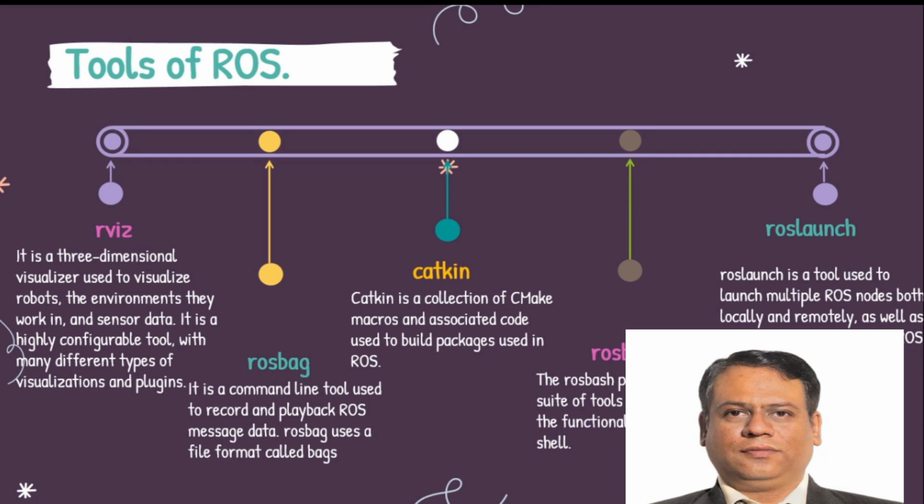And then roslaunch. roslaunch is a tool that helps to launch a ROS file. RViz is also one of the tools, whose functionality is to display the graph, but with the help of roslaunch you can launch a ROS file. A ROS file can be created with a C++ program or a program that is already written, and you can launch it. For example, when running a Python program, you go to the option called Run and then Run Module in IDLE. In the same way, a ROS application file can be run or launched with the help of the tool called roslaunch.